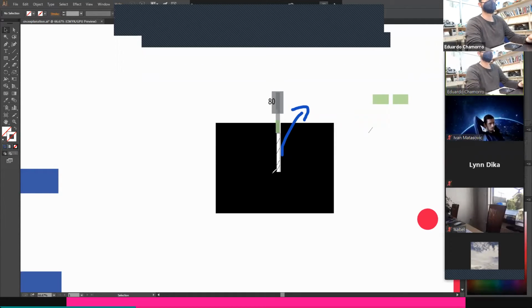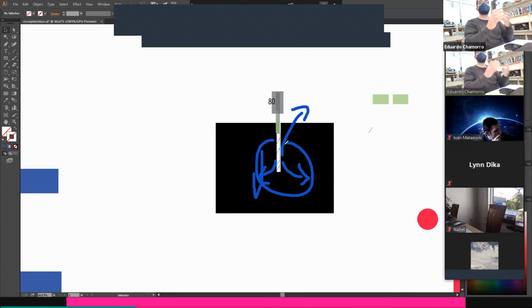So, clear all drawings. So the up cut is pushing the material up. In this case, if you are making just a hole, you can do it. What happens with the end mill that is pushing the material down? There is no space to put the leftover material. What happens when you rotate a wood stick against another wood stick manually? Fire. It's exactly the same in the end mill, but instead of a wood stick, it's a metal stick. So it's even worse.